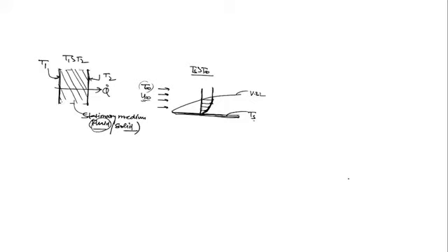It's a velocity profile. And due to the no slip condition, you know the velocity is 0 at the surface. Clear? This is y, and this is x. Now when Ts is more than T infinity, then along with the momentum transfer, along with the velocity boundary layer formation, there is also thermal boundary layer formation, or temperature heat transfer will be there. Yes or no? So listen, at the same time I am talking about the temperature distribution.